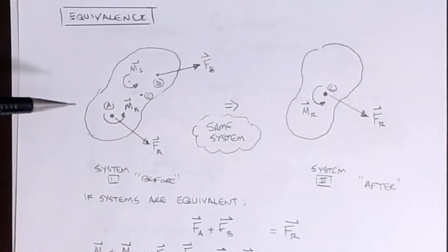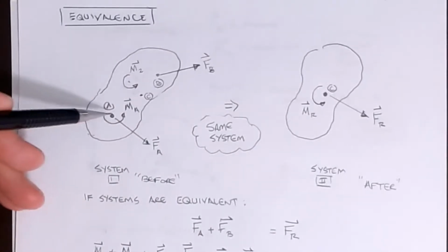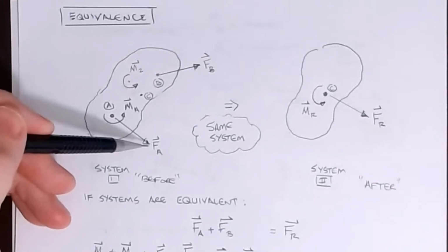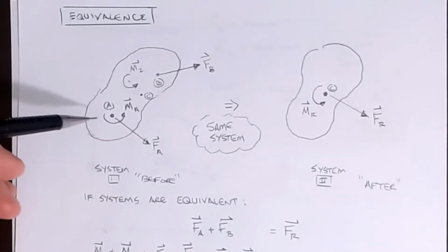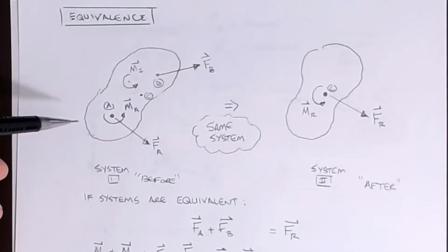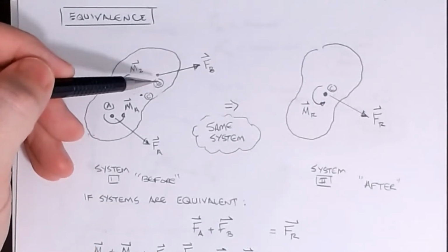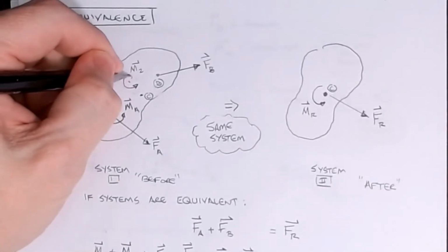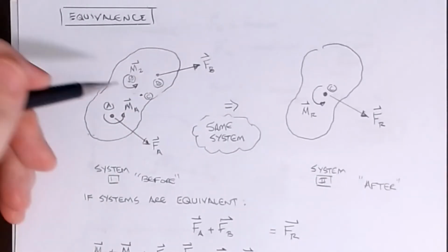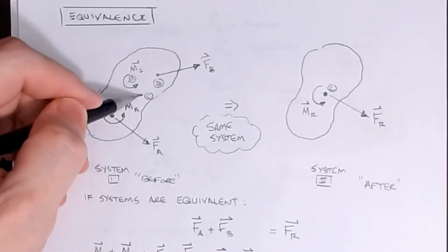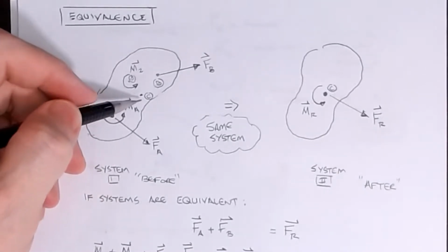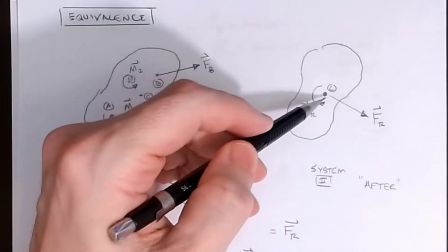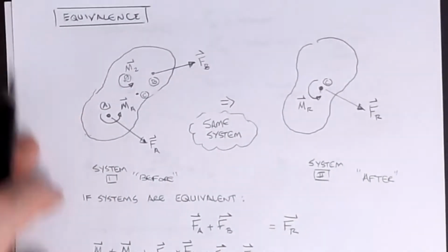So what we have here is several points A, B, and C, and let's just say at A, there's a moment and a force vector acting at A. Now again, these could be in any direction. They could be i, j, k's. It doesn't matter. The formulation is still exactly the same. At B, maybe I just have a force. There's no moment value. Maybe at some other point, maybe this is D, there's a moment but no force. And then let's just say C is a point that I'm interested in, or it's a single equivalent point. We can turn this complex system into a system of forces and moments acting at the point that I want. And that's the basic methodology.